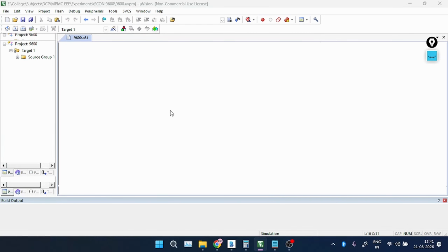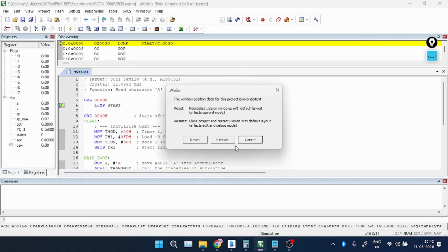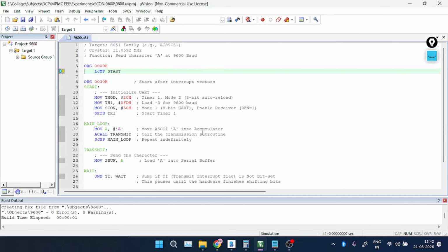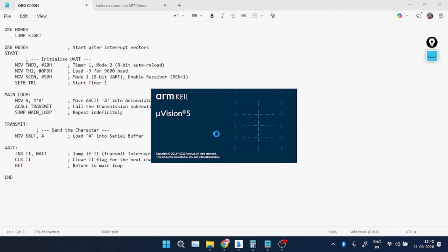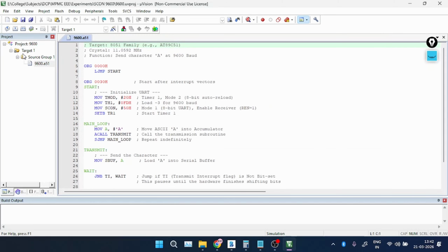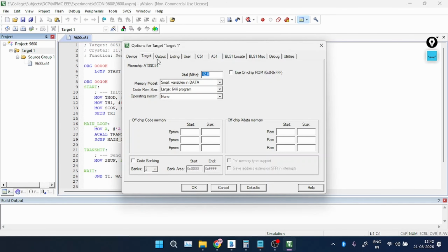Yeah, that's the problem. When you come to serial communication, you have to be exact with the frequency values. You cannot round it up to 12 megahertz; you have to keep it exact. That's the main mistake. Instead of that, 11.0592 megahertz has to be accurate.